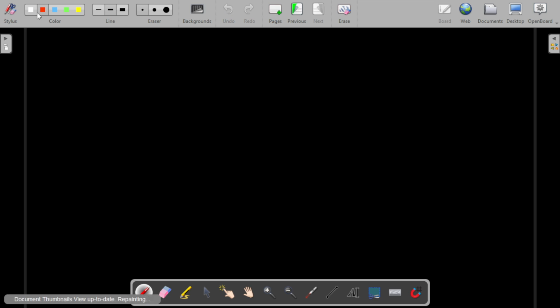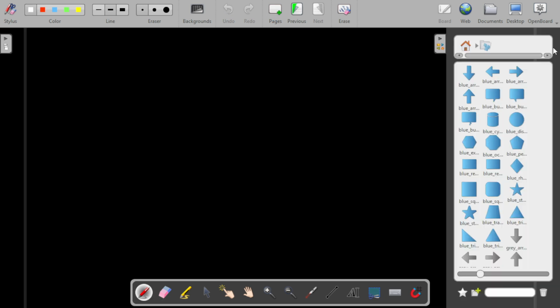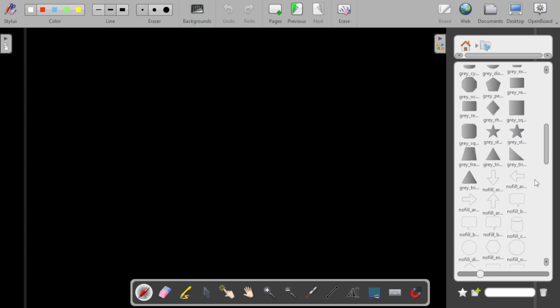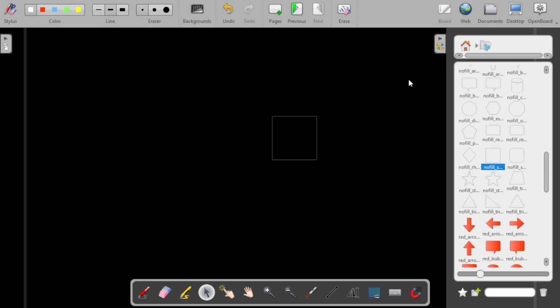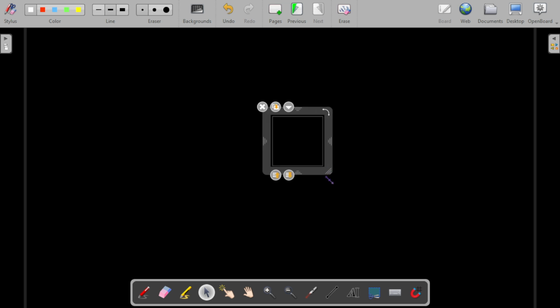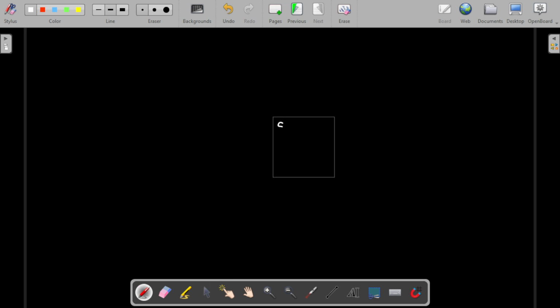Now let's see how this can be drawn as a diagram. We already have an SR flip-flop, so let's bring that to the table. The inputs are S and R, and the outputs are Q and Q bar, and we have also given the clock input. In order to convert this into a JK flip-flop, the S input needs to be J Qn bar, and the R input needs to be K Qn.